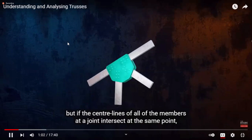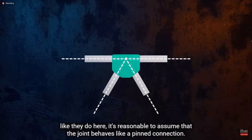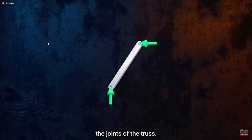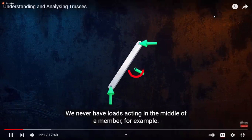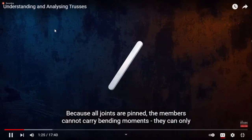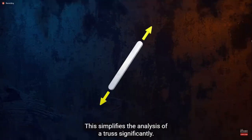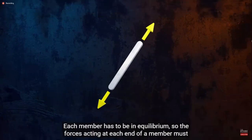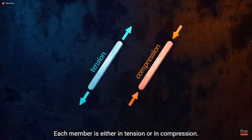This assumption must be very, very clear. If the center lines of all the members at a joint intersect at the same point, like they do here, it's reasonable to assume that the joint behaves like a pinned connection. The second assumption is that loads are only ever applied at the joints of the truss. We never have loads acting in the middle of a member, for example. Because all joints are pinned, the members cannot carry bending moments. They can only carry axial loads. This simplifies the analysis of a truss significantly. Each member has to be in equilibrium, so the forces acting at each end of a member must be equal and opposite. Each member is either in tension or in compression.